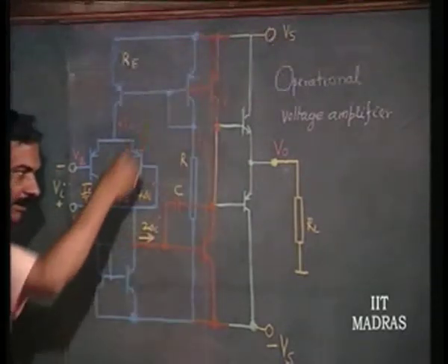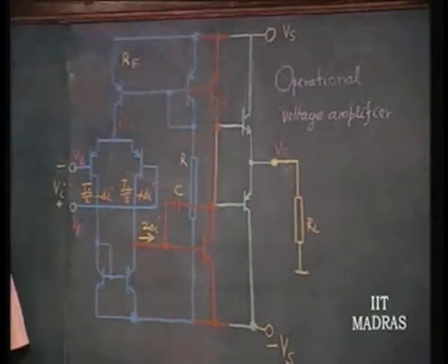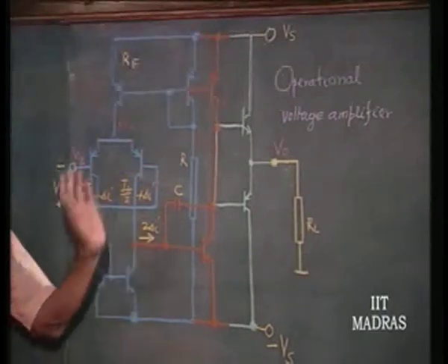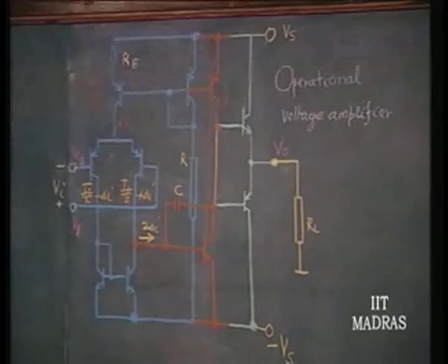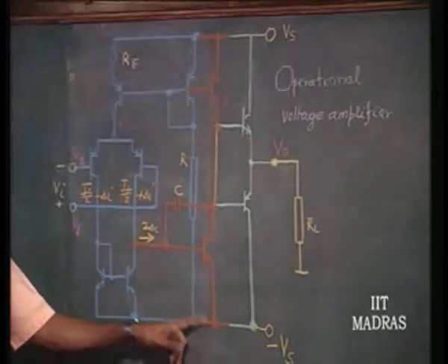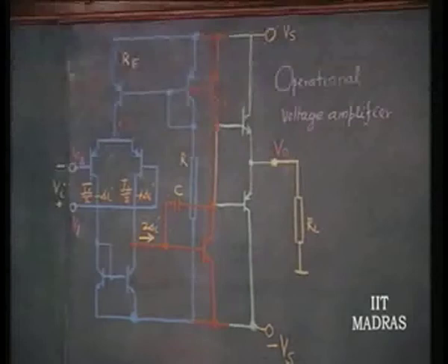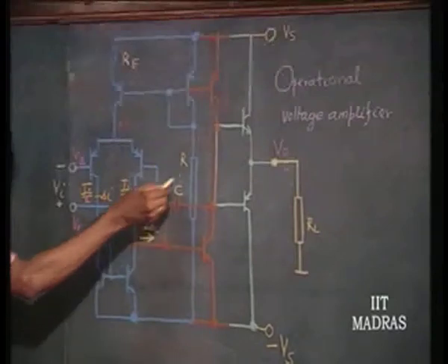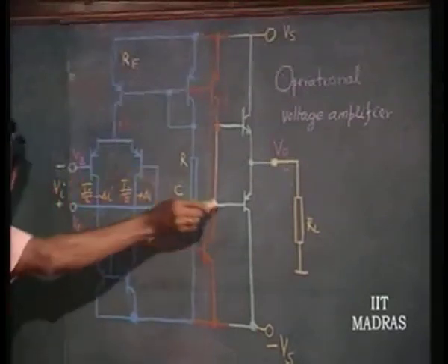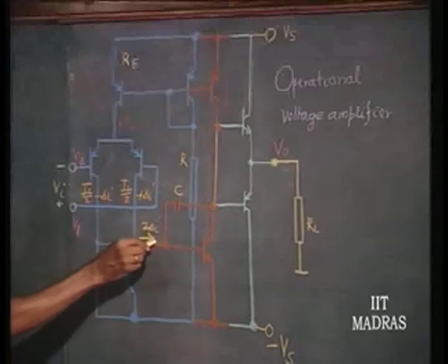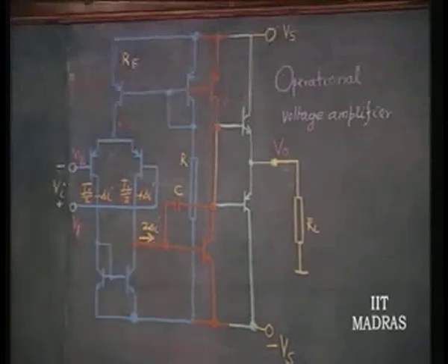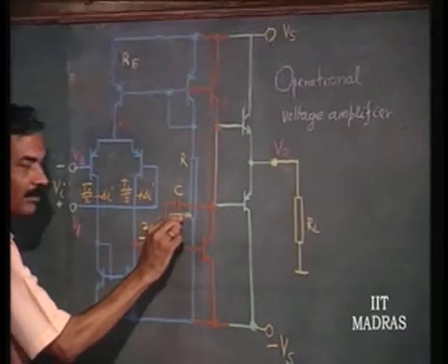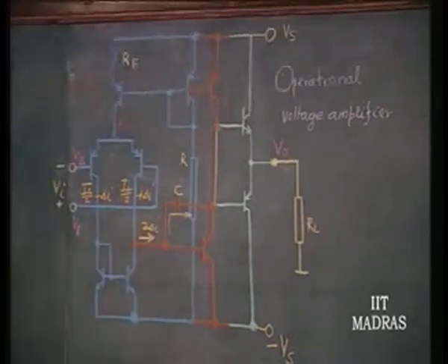Now, I can replace this whole thing, only for the signal picture, as an amplifier, the op amp itself. This is grounded, and you have a situation of an amplifier with very high gain, because most of the gain of the amplifier is concentrated here, neither here nor there. So, this 2 delta I is going to flow through the capacitor because of the Miller effect anyway.